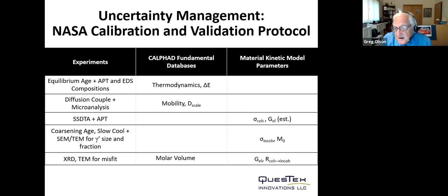And this was done in the context of process optimization for dual microstructure heat treatment of 3rd generation disc alloys. So for each of those new alloys, we first brought them to equilibrium and compared the predictions of the gamma prime compositions and fractions at equilibrium to down-select the most accurate database available. And if necessary, to get the exact phase fraction, we would apply a rigid energy shift in the GES module of Thermo-Calc to get very accurate phase fractions.